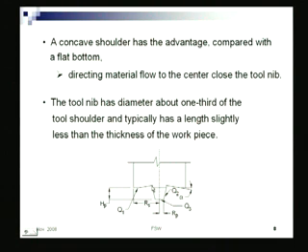Firstly, it has some space here, right. It has been concaved with an angle of alpha. So there is a small additional gap where the extra metal goes, when this nib is plunging into the plate, some material is getting displaced, so some metal will tend to come out. So when the metal is tending to come out, because at the back you have a backing strip, is holding the plate.